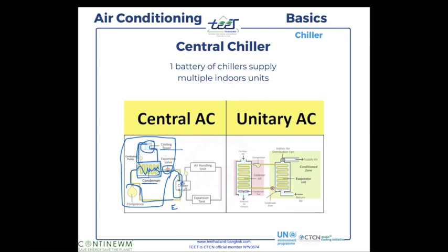This is the first part. The second part is the water that will be used from the chiller. You have a heat exchanger, so you have cold water, okay? And we use this cold water to go into the AHU or FEU or four-way cassette or whatever, but instead of having the evaporator directly with the refrigerant fluid expanding, we have water.